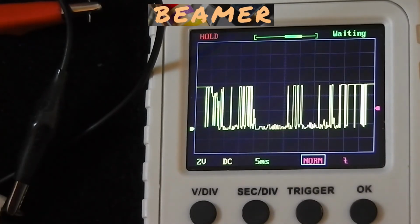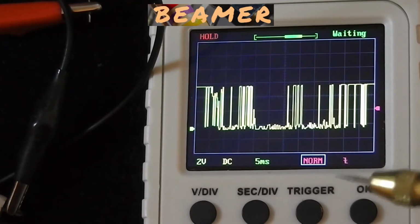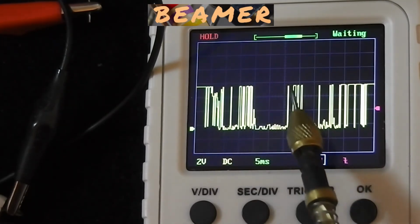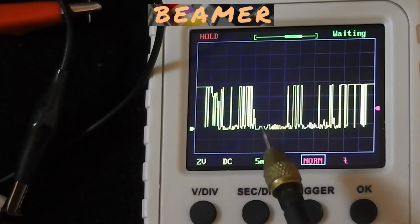Well, if you've got a CPU polling this switch to work out whether it's been pressed or not, and the polling is not inhibited in some way, you can see how the CPU, because in a gap like this of 10 milliseconds, a CPU could be running 10 million operations, a modern CPU.